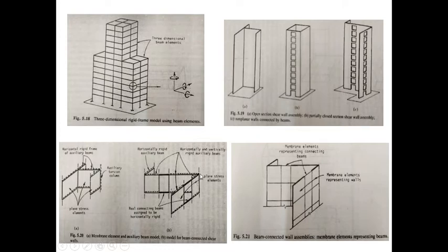And here at the ends, at the joints and corners, especially in this figure, you can see there is an auxiliary torsion column. These are the plane stress elements, and this part is the real connecting beams, which is assigned to be rigid. 1, 2 here, and these dotted lines on top are horizontally as well as vertically rigid auxiliary beams. So this is for the membrane element and auxiliary beam model. Here you can see the beam element and the membrane element.